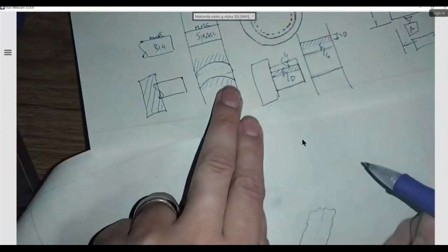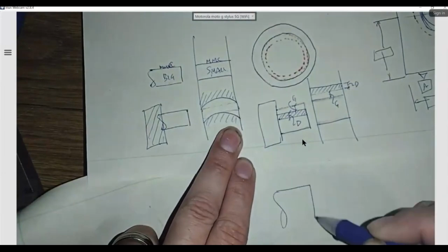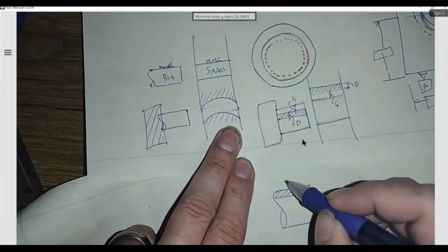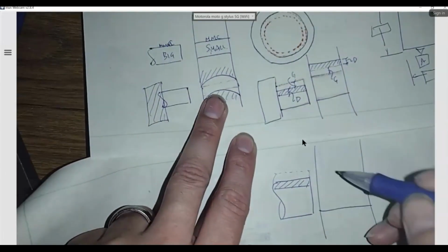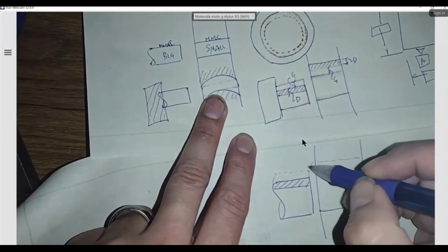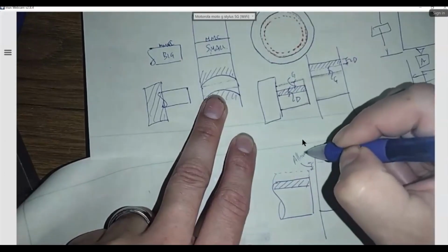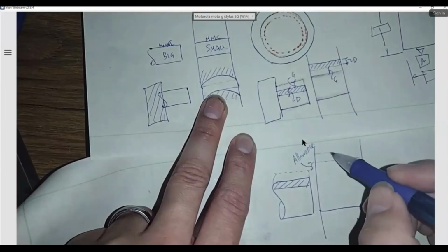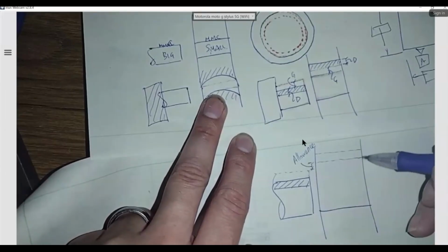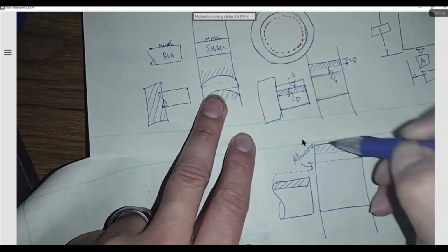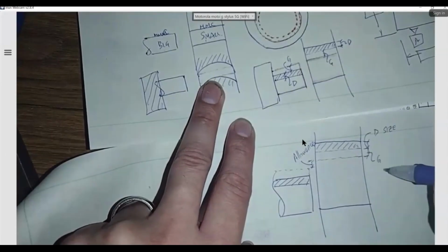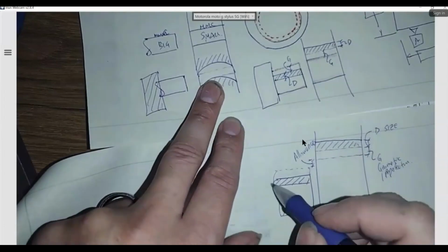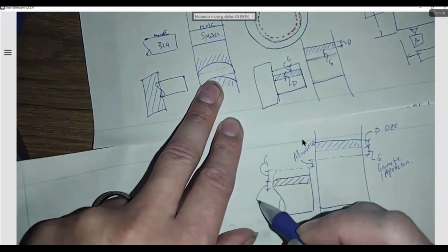To make it simple, I'm going to make it even bigger. So I'm going to grab the pin. I'm going to get dimensional tolerance, and then I give it a little bit more for geometric imperfection. I'm going to grab the shaft. I'm going to give it a little bit of gap from here to there. Call it an allowance. And then this guy here will be the wiggle room for the hole to get out of imperfection. And then give it a tolerance here for the size. So this is the D, that stands for the size. This guy is for the G, which is for geometric imperfection. The same thing with this one. This is the G, and then this one is the D.